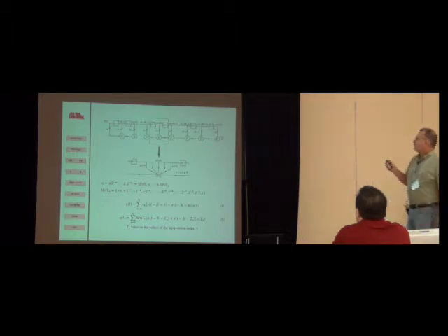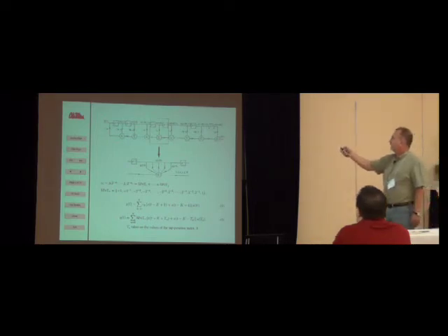The problem with this filter, as it's written, from the point of view of making a filter that's going to work in real time, is that multiplications are very expensive in time. To actually implement this filter, I've got to have 2K plus 1 multiplications. And if you're trying to do this in a sample period, that's often not possible if you're talking about a very high frequency of operation. And so